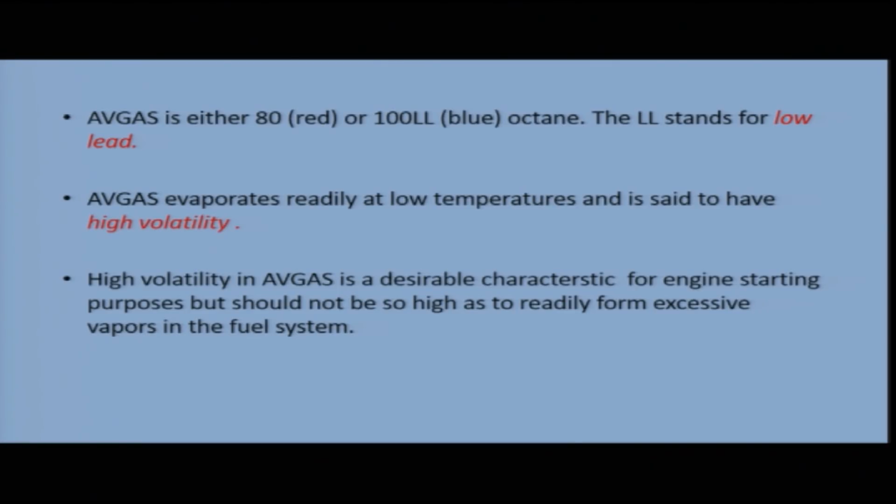It is a desirable characteristic for engine starting purposes because it helps in combustion, but it should not be so high as to readily form excessive vapors in the fuel system. Now, if the fuel is highly volatile, it may cause a negative effect also. It may vaporize very easily in the fuel lines and cause vapor pockets, which may finally result in fuel starvation. So, the aviation gasoline should have high volatility, but it should not be so high that it forms excessive vapors